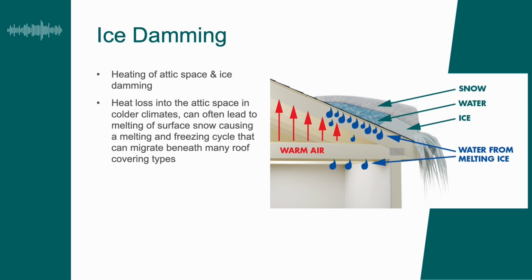They either just overlap, they may be semi-interlocking to some degree, but most of them are not sealed and locking systems, such as a metal panel that's got a mechanically rolled seam. Now that's a totally interlocking system. But ice damming can cause some real damage when it starts to occur.